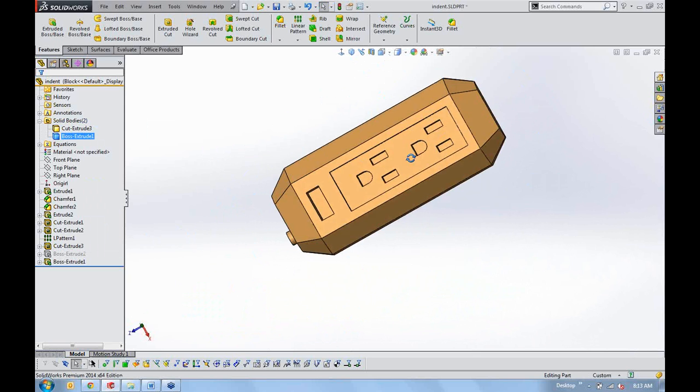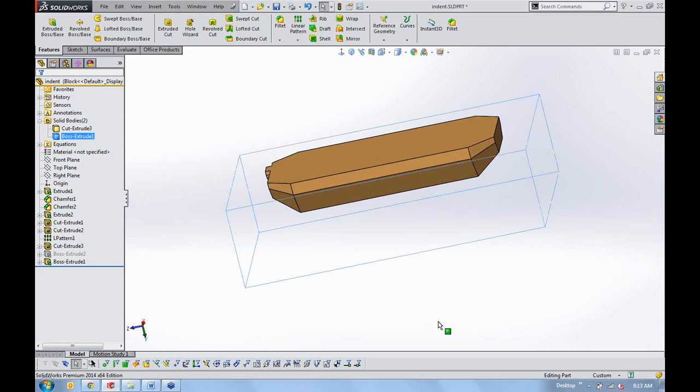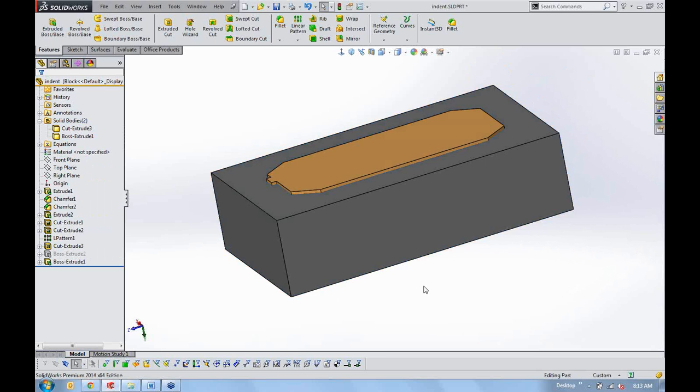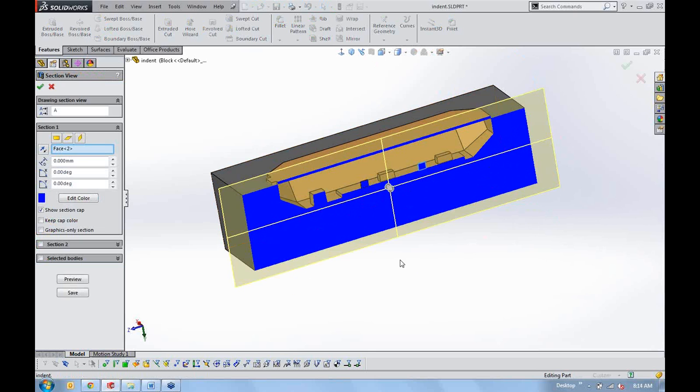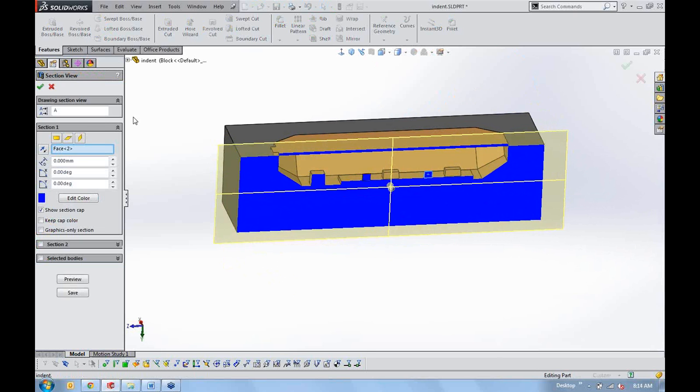And the indent feature is a relatively newer feature. I mean, it's been around for probably 5-6 years at this point. But it's kind of an enhancement to the cavity feature, or the combine feature where you combine two solid bodies, but it has a lot of really cool tools in addition to that. So I have this block here, and I actually embedded it into another block without merging bodies, obviously. So if I take a cross section, you can see both bodies here look something like that.